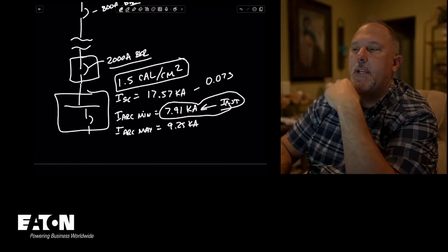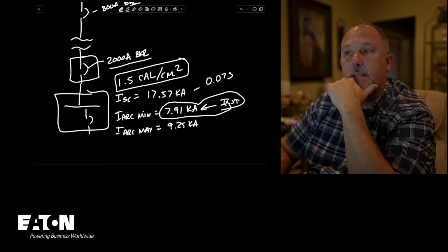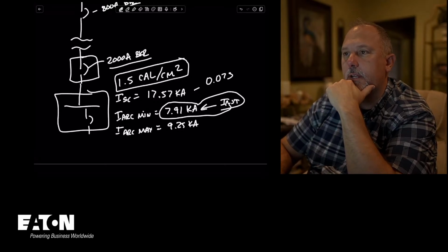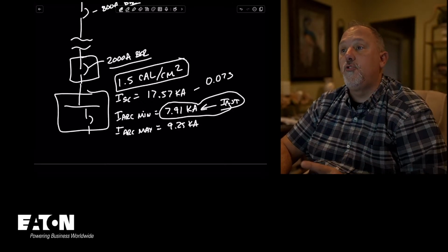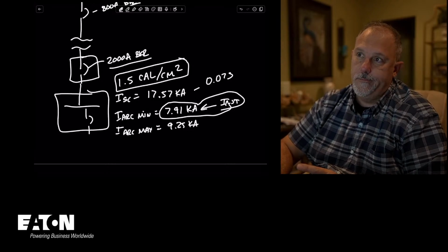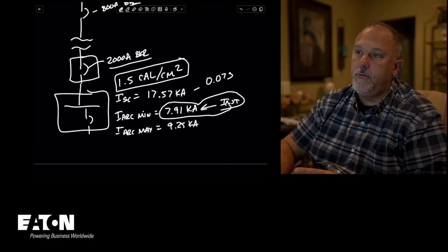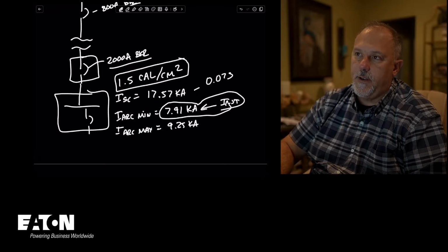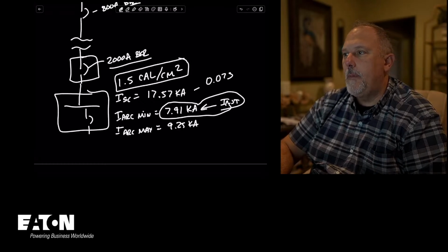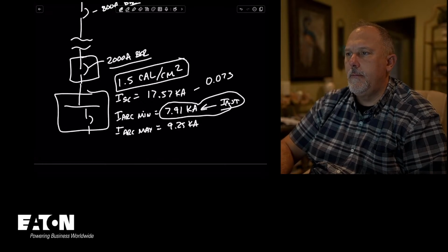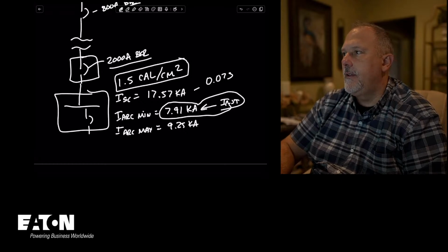So what we did, I'm just going to go back and pick up. I'm going to take a look at a different option. That's my RD, my 2,000 amp breaker. Now, if I did two 1,200 amp panels, which you could do, let's take a look at the ND. If I did two 1200 amp panels on the secondary, there's my 1200s.